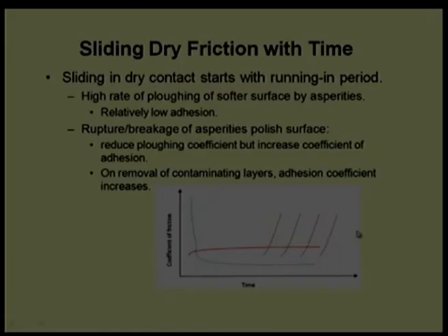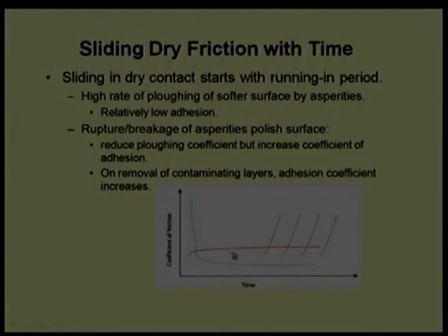That is why we are keeping these as imaginary lines. They depend on the load condition, on the temperature, and on whether the lubricant layer was initially there and got removed from the surface because of starvation, pump failure, misalignment, or some other reasons. So, there is a possibility of this kind of hypothetical lines.